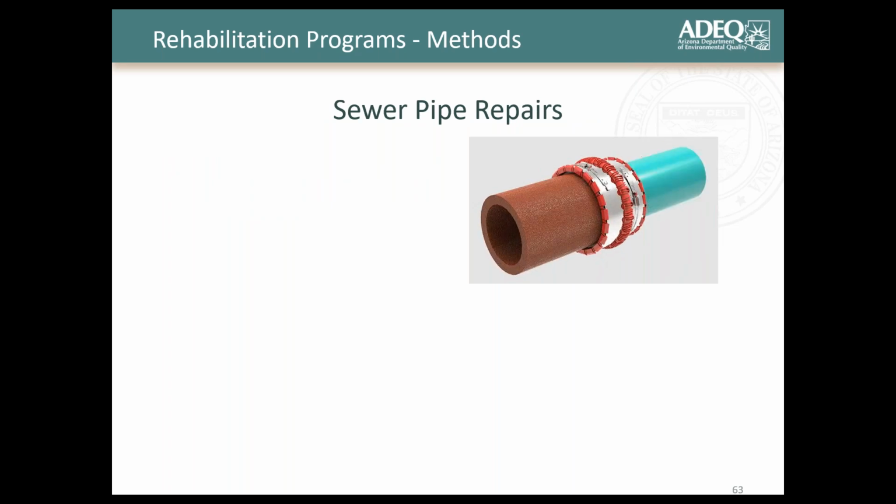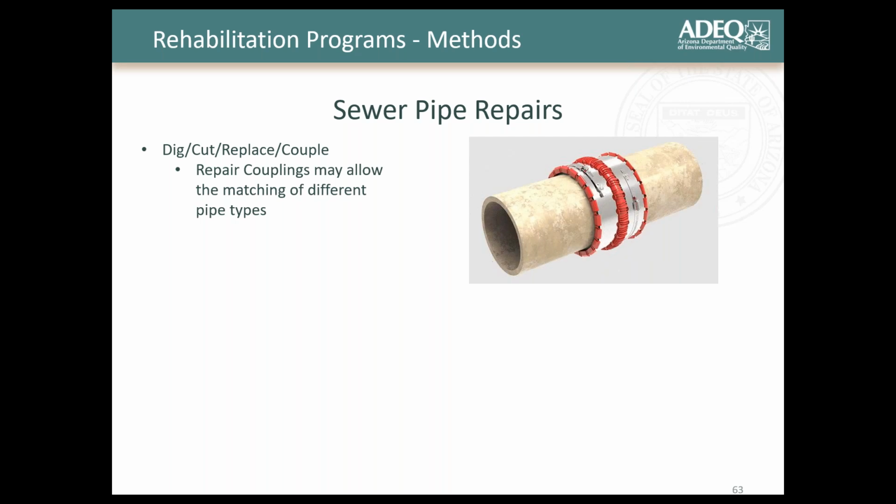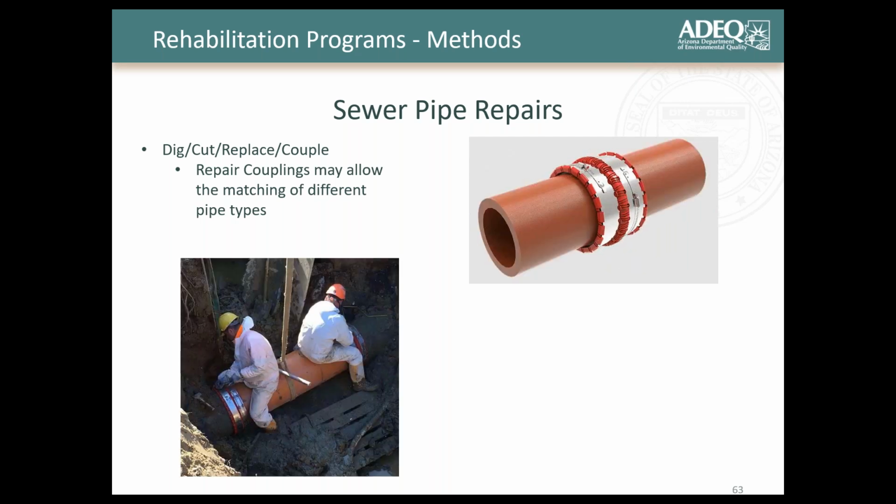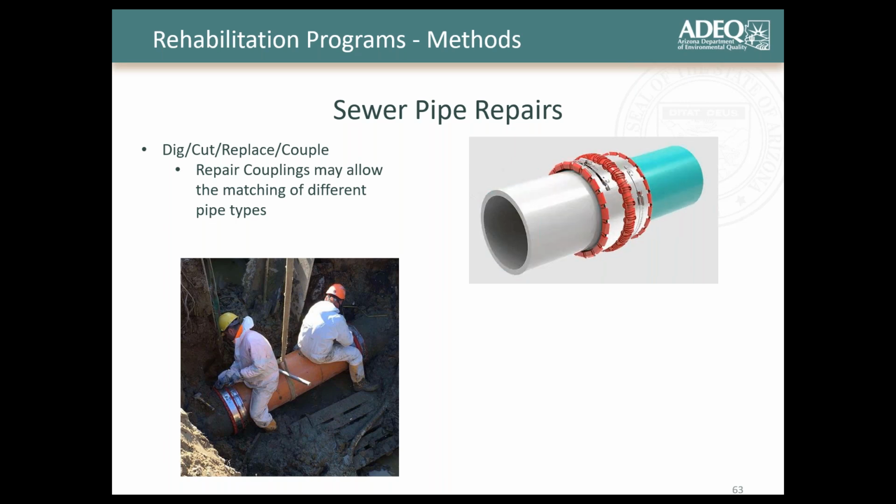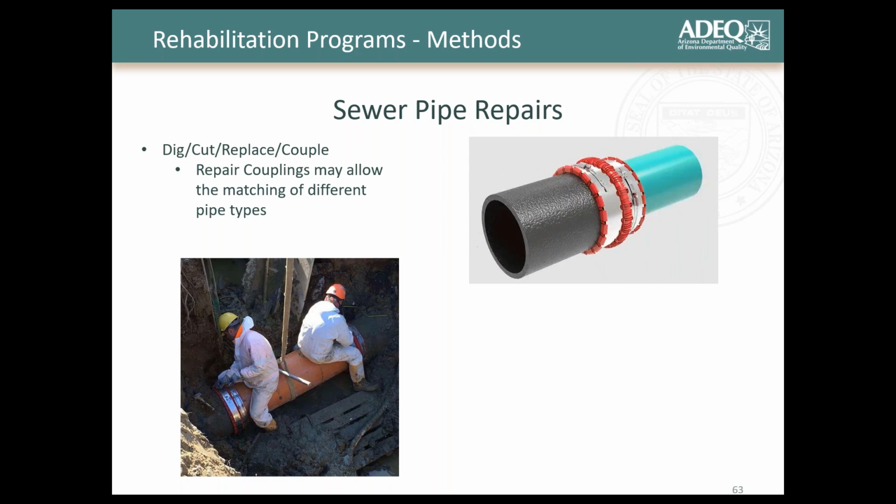And of course, your more traditional methods, right? You dig, cut, replace, couple. This is more what I was used to getting involved in. Just repair couplings. They allow you to match different pipe types too, so it's a nice feature.